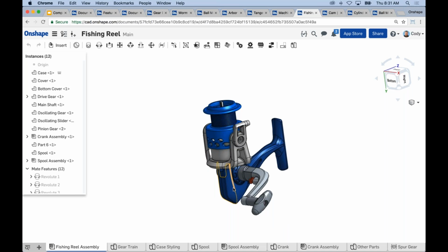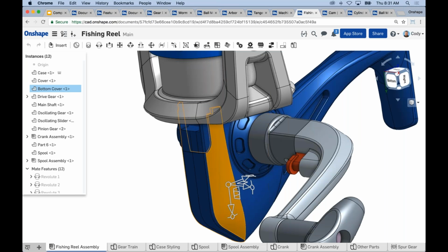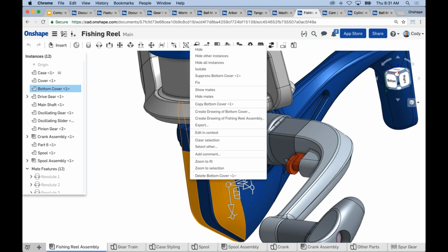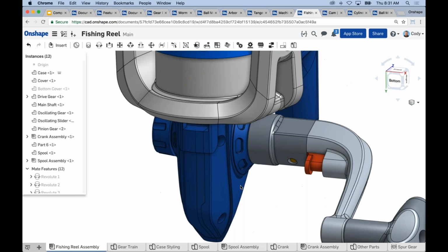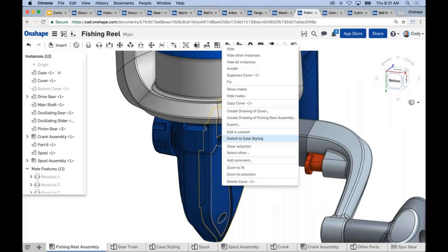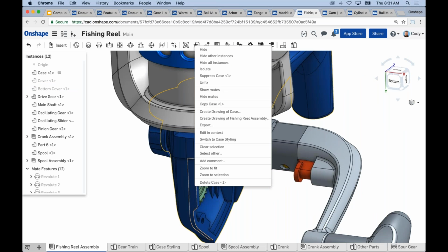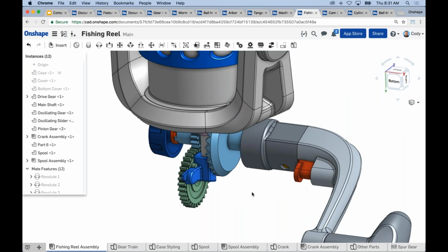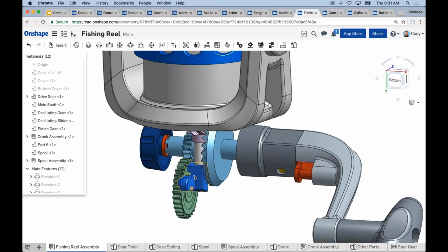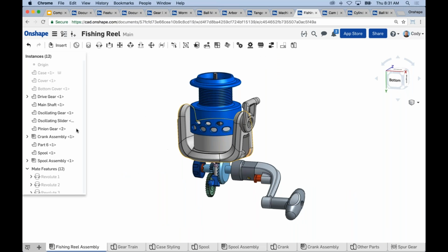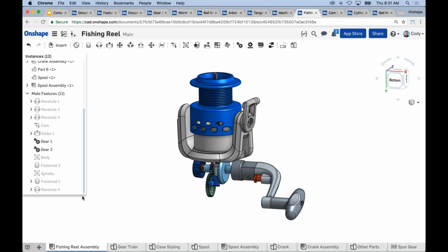What's really unique about it, if we start to hide some of these shell pieces here, is that this design allows you to put, similar to a path type relationship, one of these gears inside of a part. And when you rotate, let's go down and rotate, you'll get that up-down movement.